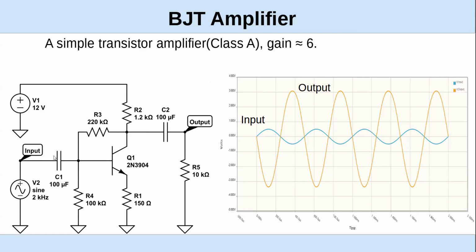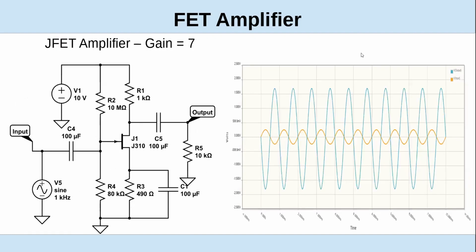But in this circuit, basically you're using the R2, R3, and R4 network to establish the bias point, which is about in the middle, which would be around 6 volts. And you normally use a little emitter resistor that helps stabilize it. It does an offset voltage. That's a pretty standard configuration. It's one of the things I learned in college decades and decades ago.